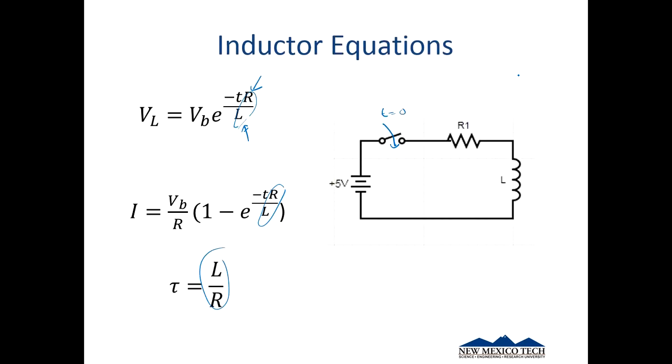And just to make things convenient for us, because an inductor is really just a coil of wire, their series and parallel combinations behave like resistors. So if I had some circuit with an inductor here, and this was 5 henries, and this was 7 henries, because these are in series, we would add them. So we could represent that as a 12 henry inductor. The parallel combinations work the same way, where 1 over L equivalent would be 1 over L1 plus 1 over L2 plus, you get the idea.